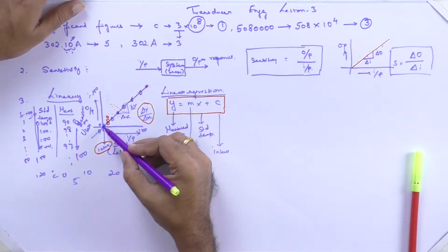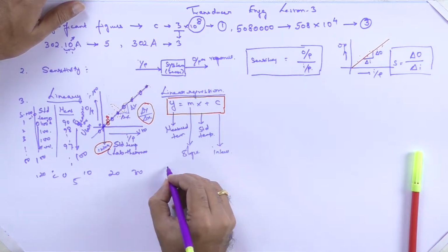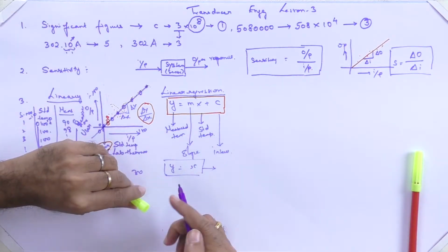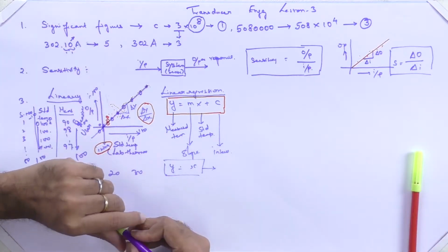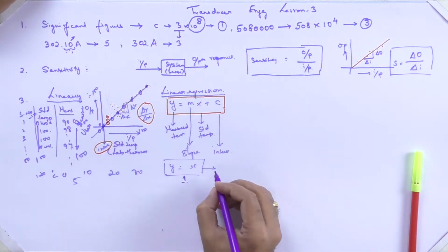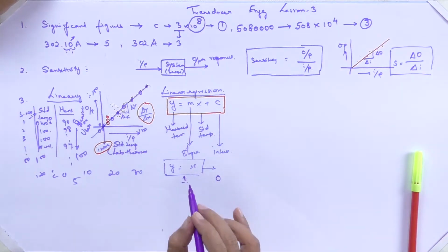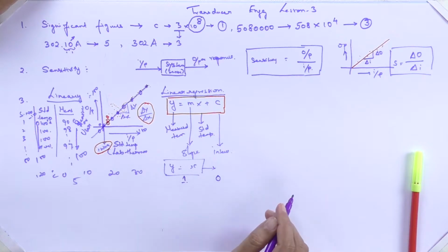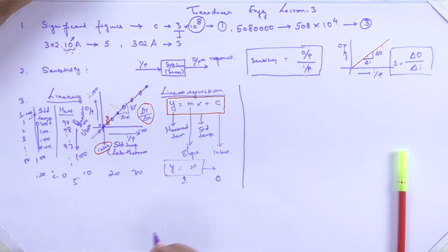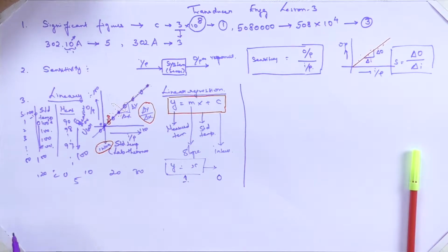Mainly, using this straight line, the ideal line you should get is y = x. But this is an ideal condition, and you won't get it. Instead you have your slope and intercept, and in the ideal condition the slope is equal to 1 and the intercept is equal to 0. How near the equation is to a slope of 1 and an intercept of 0 gives your real system. This is linearity. So finally, to conclude, any system should be linear in nature. When you give some input, it should give a corresponding increase or decrease as the output. That is the linearity of a system.